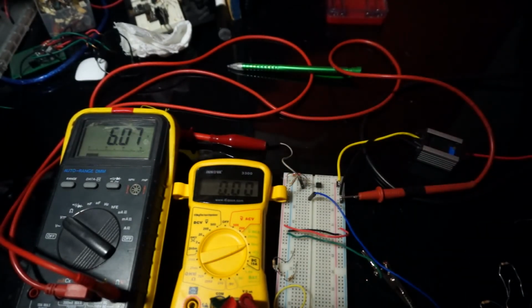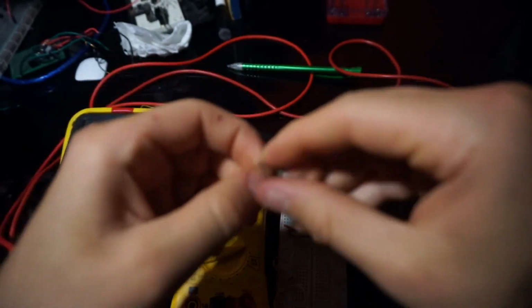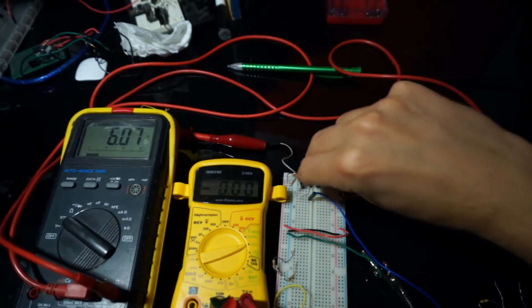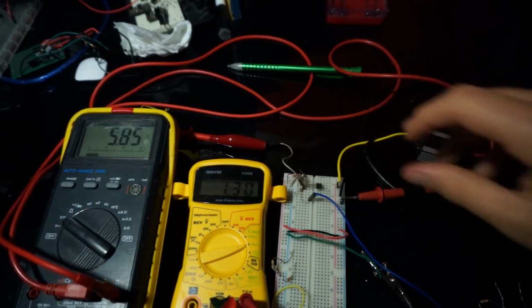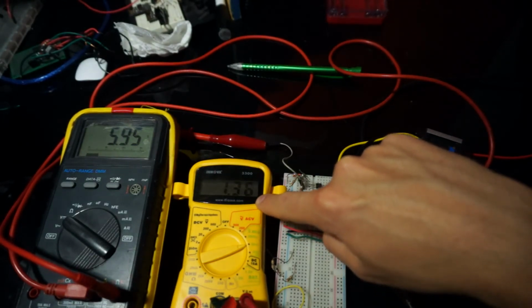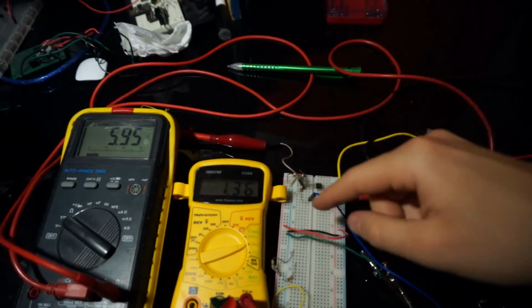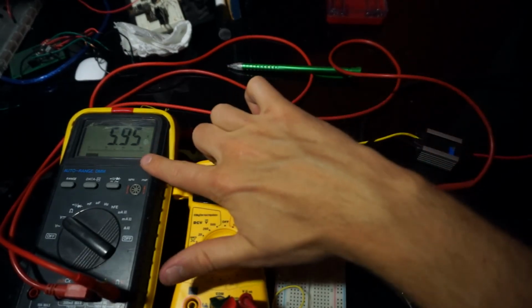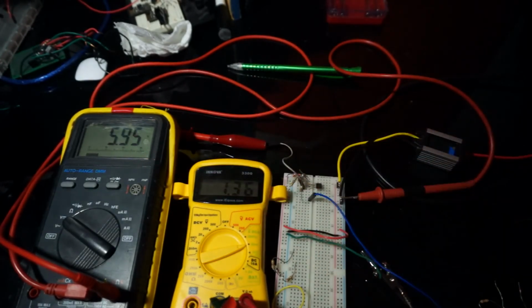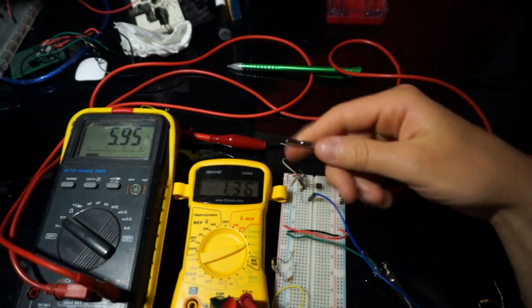But now let's go ahead and double that. So now we're going to have 4.4K. We should expect exactly double the voltage across that guy, if in fact it's still working. And what do we get? Okay, so see, the current is already starting to sag, 1.36, and we expected double the voltage, so about 8 volts, and we're only getting about 6. So that's showing you that we are already pushing the transistor out of saturation, and our constant current source has been defunked.